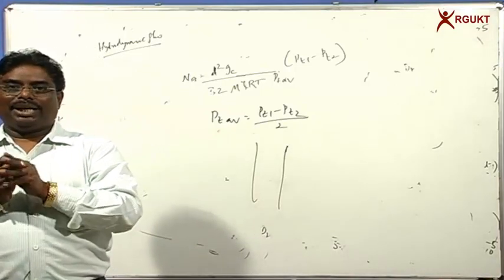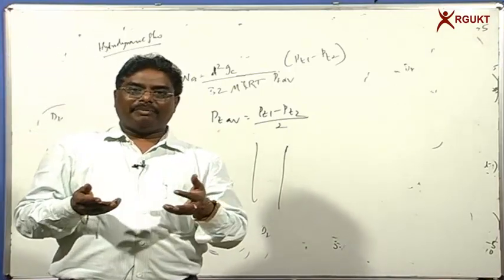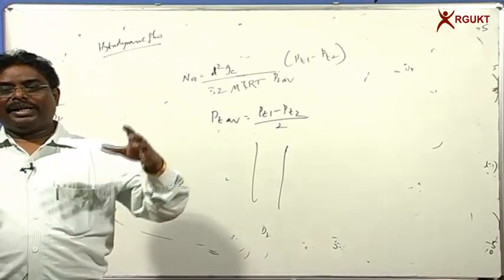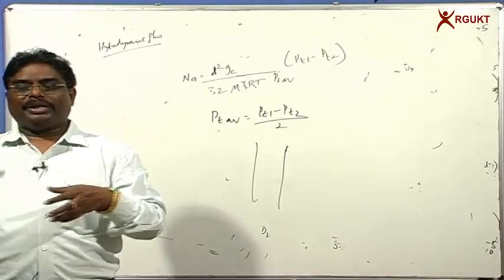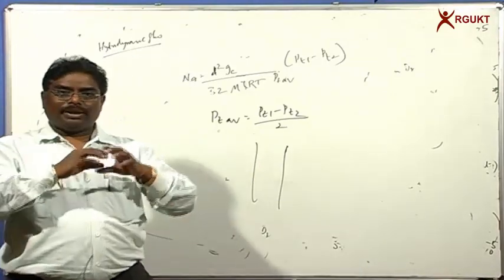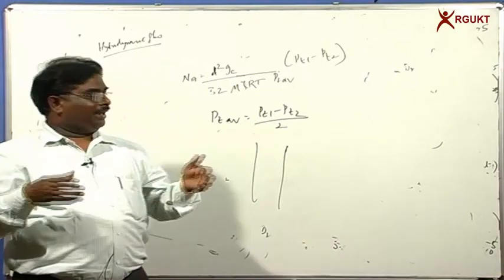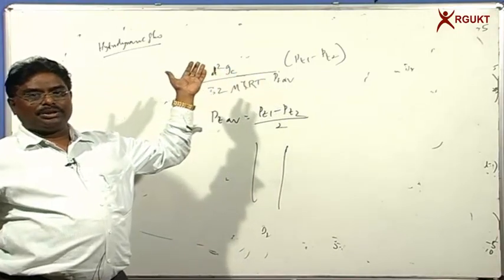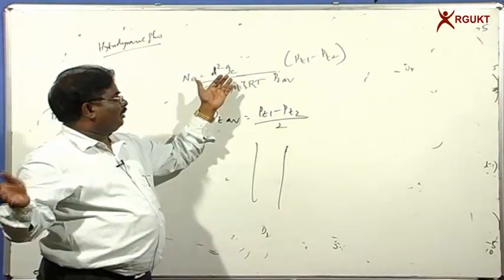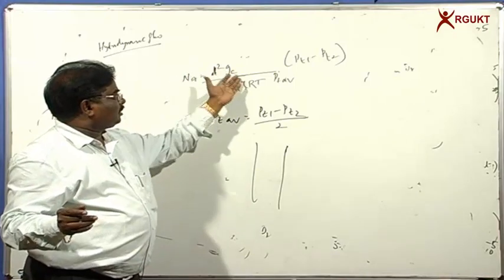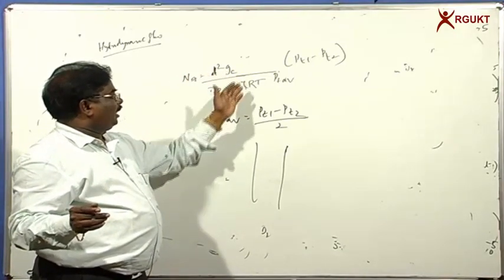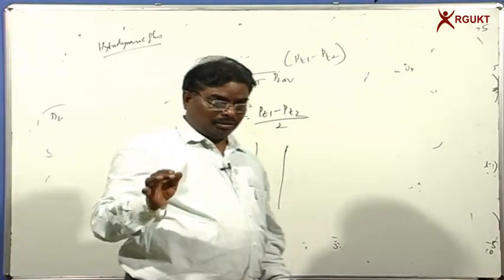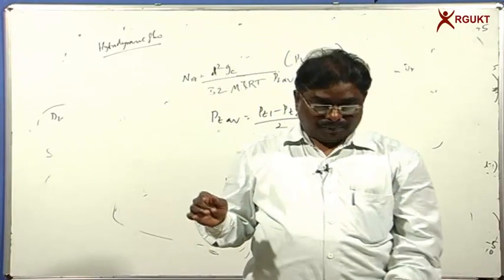Similarly for Knudsen diffusion. When you talk about hydrodynamic flow, the pore sizes are very big. It is nothing but diffusion of the material through a pipe, where the pipe has some radius and other properties. So we can use an equation similar to the Hagen-Poiseuille equation, which you derived in the momentum transfer class, for the estimation of the flux. In this case, if everything is known, one can estimate the flux value. This is what I wanted to conclude, and we have completed diffusion through solids.